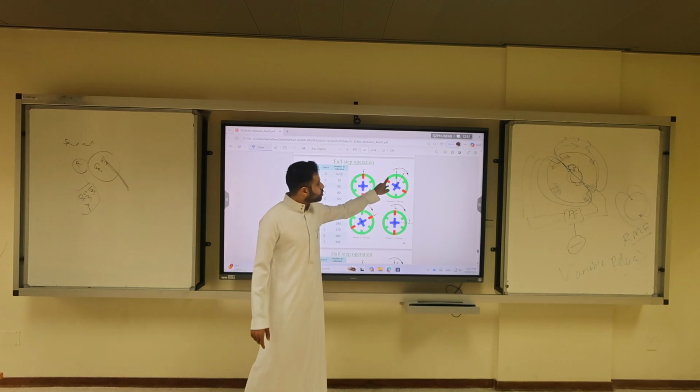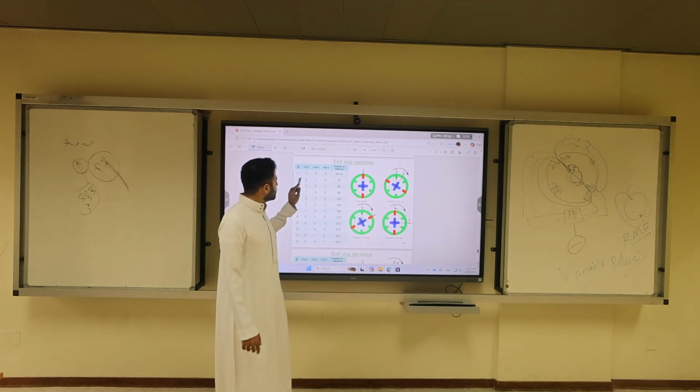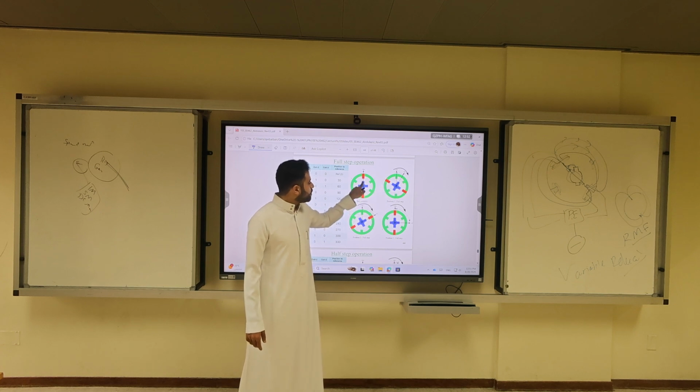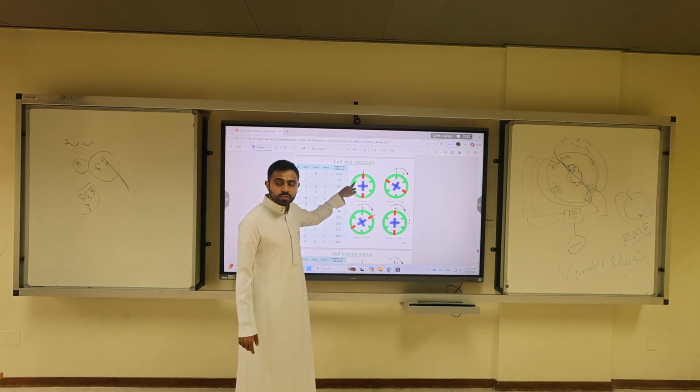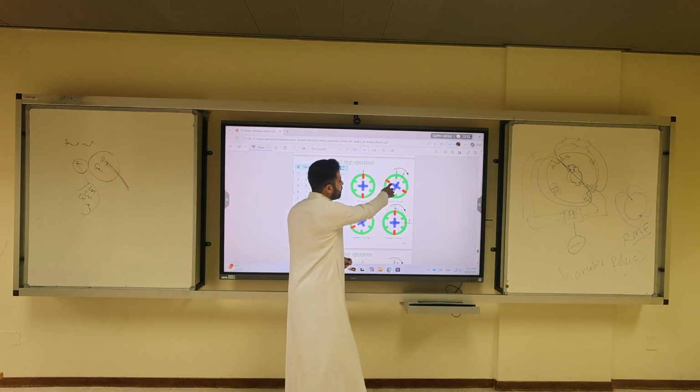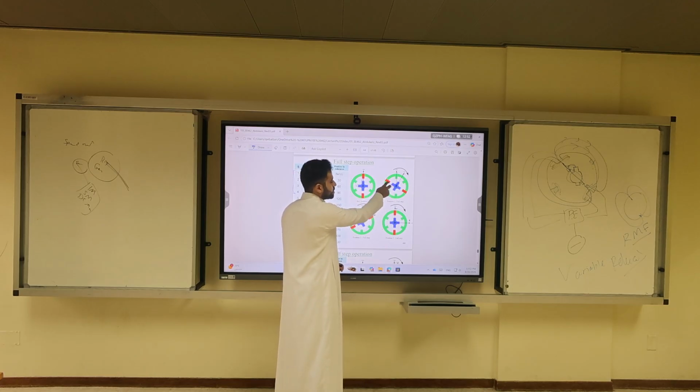Let's do coil 2, I'll do only one coil and then we'll go. Make 1 and 3 de-energized, energize 2, what will happen? Either this or that. Which one is closer? This or that? A or B? No, A. A is closer to 2. So if you energize 2, because A is closer, B will be aligned here if you energize 2.